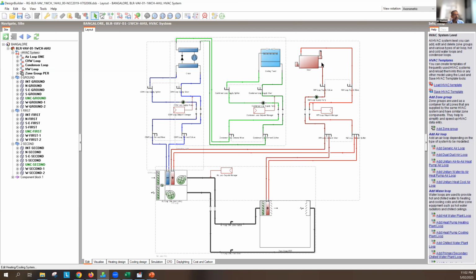Now I've shown a boiler and a heating coil, both in the AHU, and in this case, we're using a variable air volume, VAV system. And in the VAV box, we have what's called a reheat coil. Now that's not always there, but in cold countries, you have a reheat coil. In India, we probably wouldn't use a reheat coil, okay? In India, we may not even use a boiler because we don't really have too much of a cold problem, particularly in office buildings. But I've just shown it there for completeness' sake.